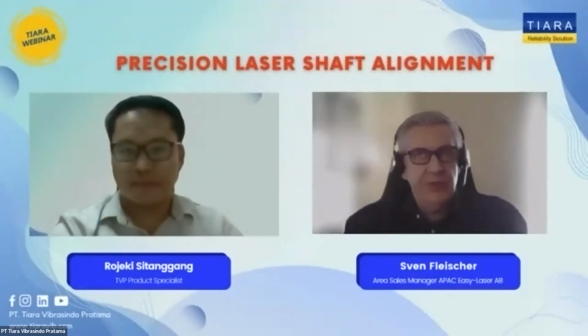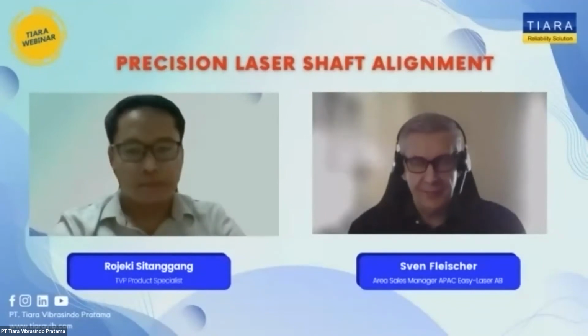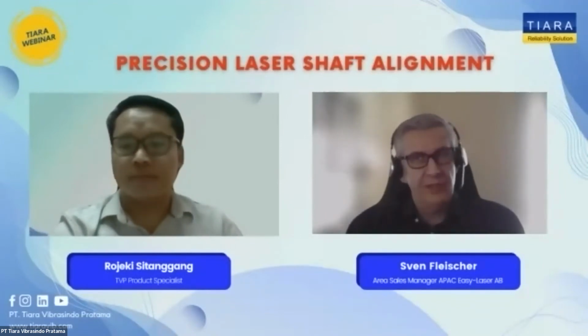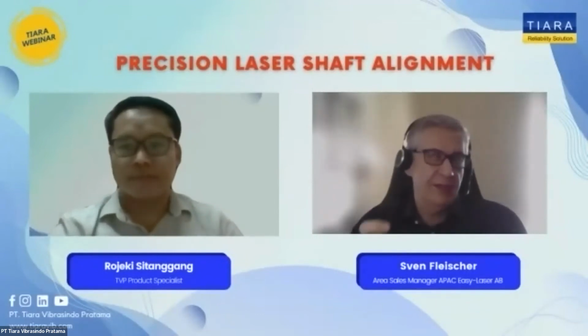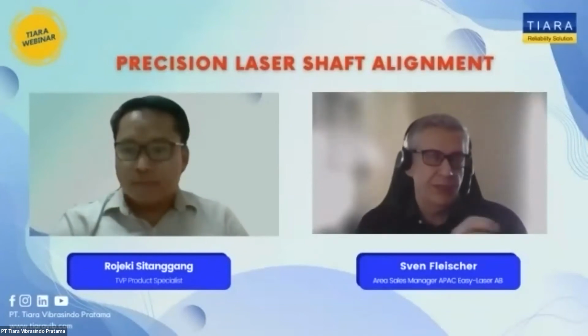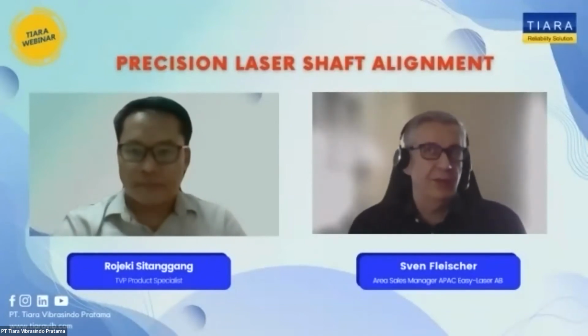Now, if you talk about level, straightness or flatness, then we would install a reference laser that is placed potentially on a tripod outside of the machine, pointing across the base or the machine part, and then we're using magnets together with brackets to put the detector across the machine and collect the readings.